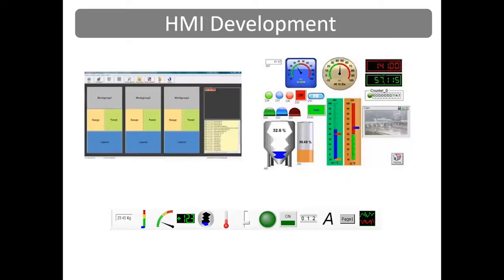An HMI is a human-machine interface. It allows you to receive information through a visual user interface like temperature, count, tank level, or on-off status. An IP camera can show you the visual overview of your application, like the state of a bridge, a river lock, or a dam. An HMI can have buttons, indicator lights, and graphics that an operator can interact with for the turning on or off of equipment, sending commands, viewing historical information, generating reports, or for just monitoring the system.